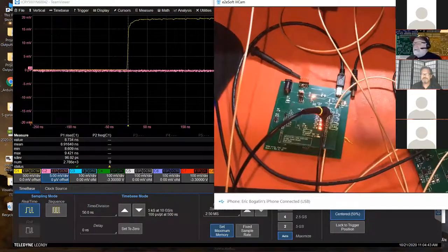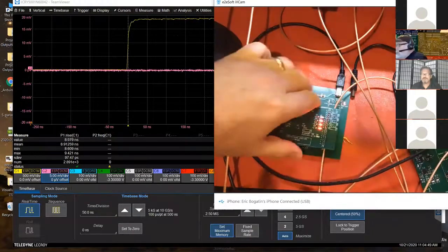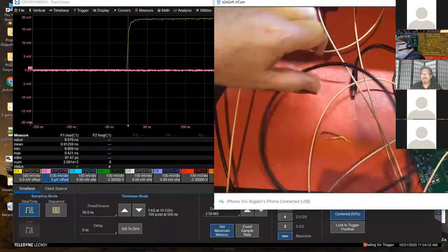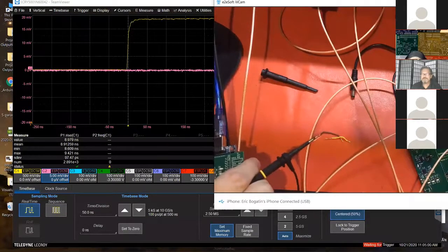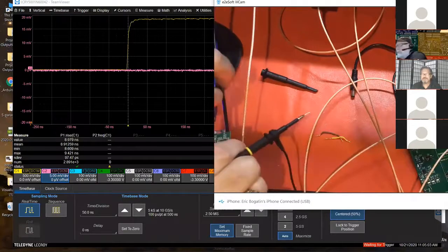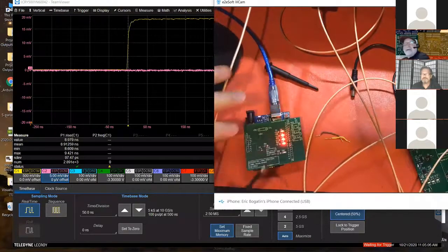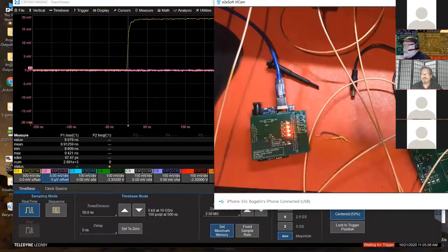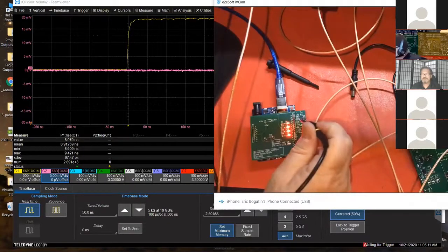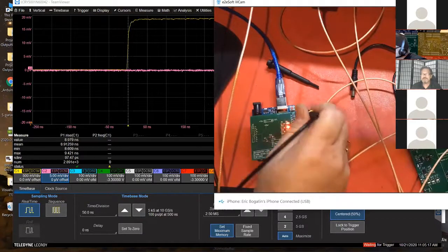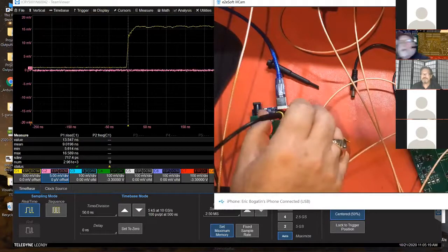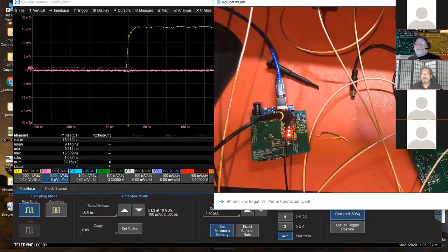But while I have this set up here, I'm going to show you an example of another board, exactly the same microcontroller board, a commercial board that wasn't designed with nice, good return paths. And here's that board. It's a commercial board. I've got exactly the same shield on top of it, drawing the same current. We're going to look at the current with our 10x probe. So we trigger the scope with it. So there's our signal coming out of this microcontroller. It's exactly what we saw before.